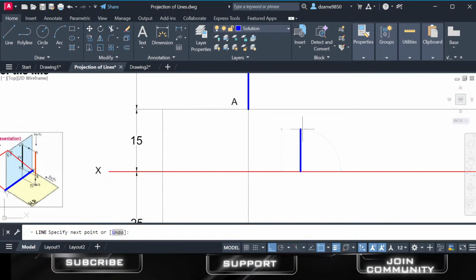If I select this line, as you can see, AutoCAD measures immediately the distance to move up to that point. If I move it up to that point, which is the horizontal construction line, what you need to do is to draw a line parallel to the XY plane, which is 15 millimeters above the reference line. That line is the line that I've just put on here.